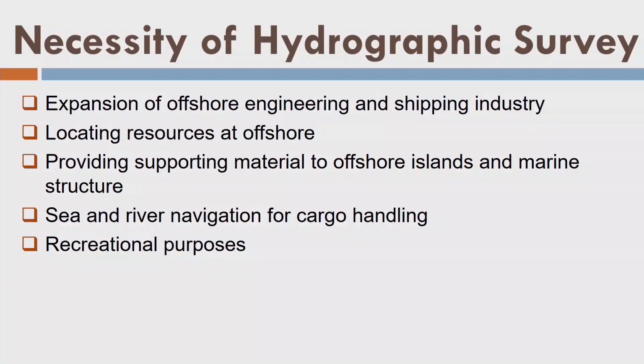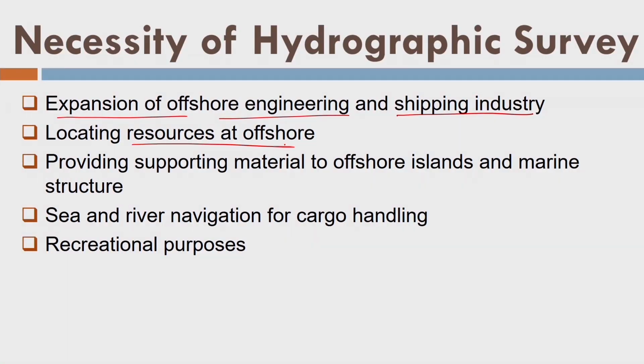What's the reason? The reason is that we want to expand the offshore and shipping industry, and if I construct some structure over some sea coast, I need to have data of hydrographic survey. What is the material available, or what is the material that has to be cut from the available surface. Then we have to locate resources like oil and gas wells in the sea offshore sites. For that also I need to bring boats or staff members for the drilling, and for that purpose we also need this data of hydrographic survey.